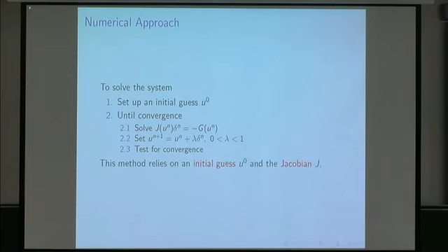It's a lot larger. But in 3D, it's also a bit harder to come up with a good initial guess, and your Jacobian is very large. This is why people sometimes use Krylov methods: instead of inverting your full Jacobian to get this result, you set up an iterative way to compute the inverse.